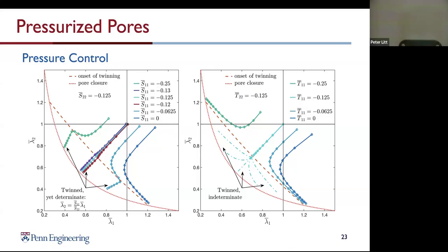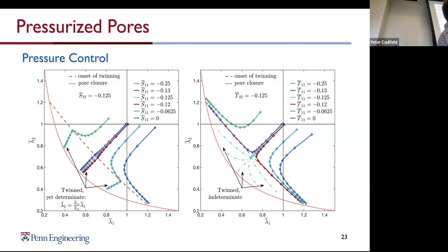And what you see is you just get a small perturbation in the deformation path that you get if you applied hydrostatic tractions. But if we do the same thing with the Cauchy type tractions, because you can't support any normal stress difference, while they start off very close, they end up in drastically different configurations because you have this very slight, ultimately infinitesimal difference in the applied tractions on each surface. So it has these interesting behaviors, these big changes in shape, this high sensitivity to the loading conditions.